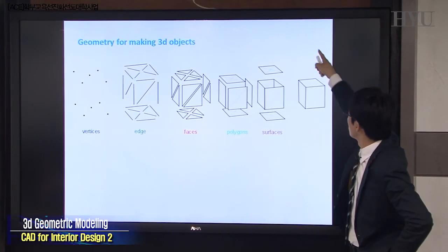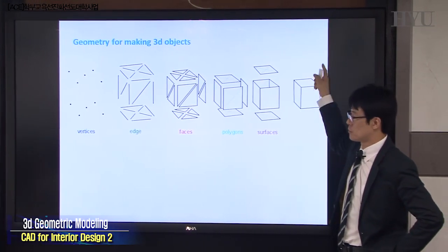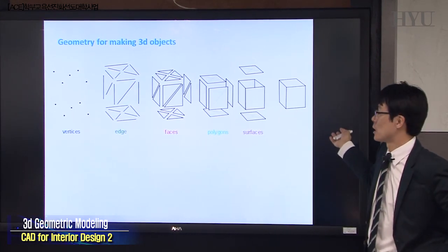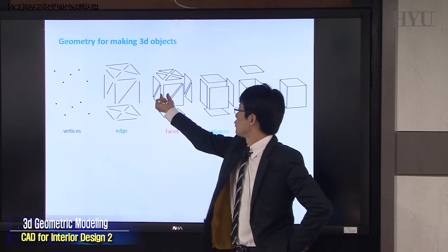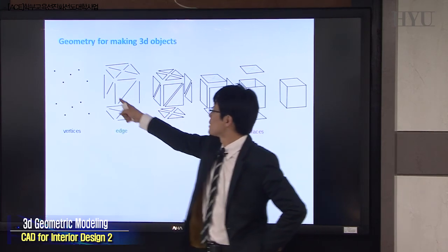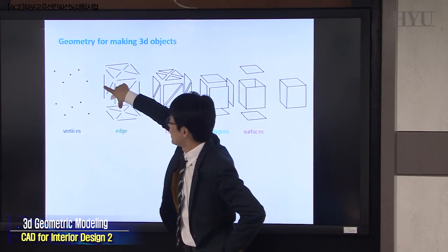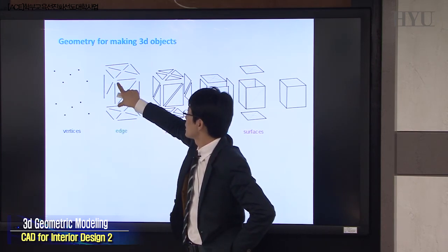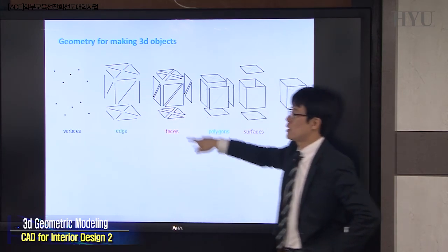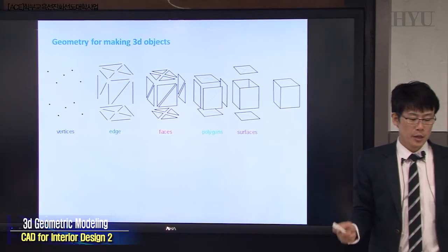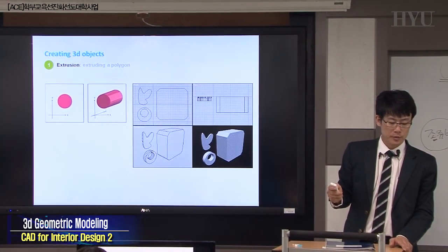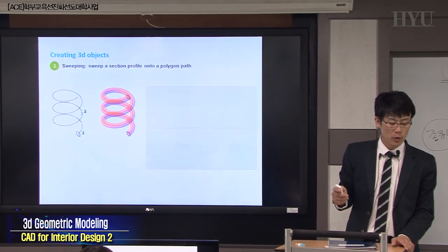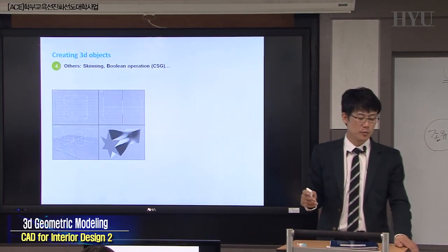Then this shape is going to change like this, a kind of wedge-shaped box. What if you move or rotate the line here, the edge here? What if you rotate the line or scale the line? You can easily control the box shape. That is the so-called editable poly. You can control polygons and their subgeometry.